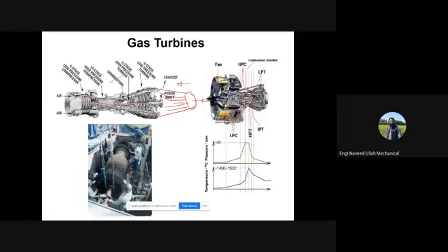If you remember, I told you that when the aircraft lands, it is still having too much speed, right? So it is not very easy to apply brakes there. The conventional brakes are applied, but at the same time we actually have air brakes there. Some parts of the airframe are also used to decelerate the aircraft. But the other important thing is the operation of the thrust reverser.